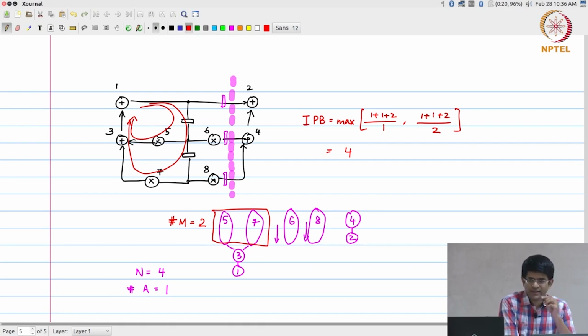Yeah, so that's a good point. Generally speaking, the rule of thumb that is used for pipelining is, if I have a long chain, then pipeline in such a way that I am able to break that chain into equal sized parts, so that the overall critical path reduces, right.